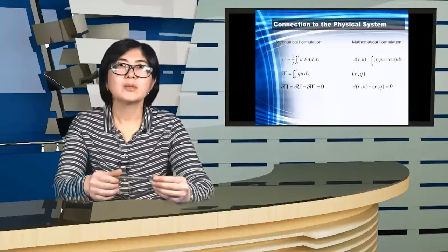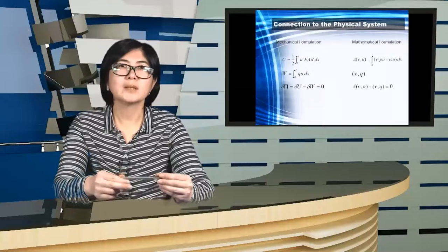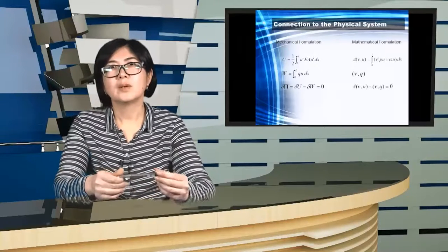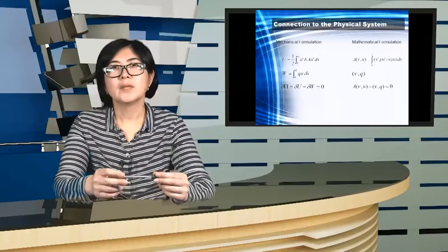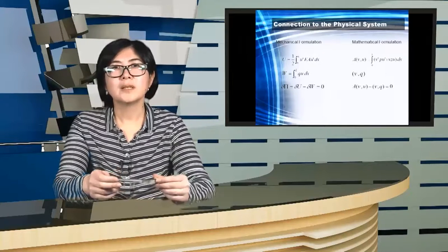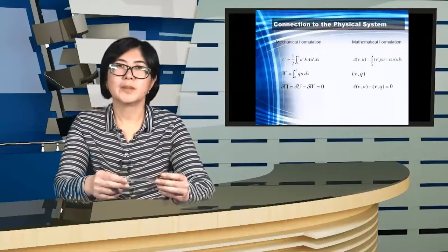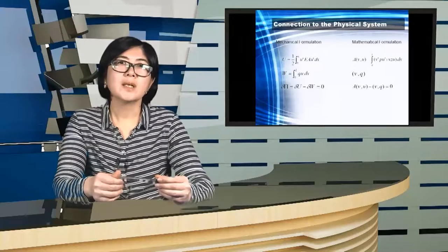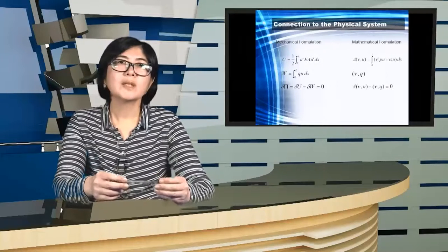External work. The two different expressions obtained for the external work are clearly equivalent if V is used instead of U. You see on your slide the weak form. Finally, comparing the weak form equations obtained by the two analyses, we clearly see that they describe the same main principle. It is that the variation of internal energy has to be equal to the variation of the external work.